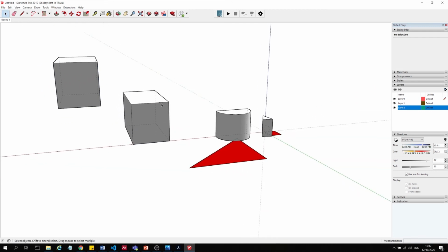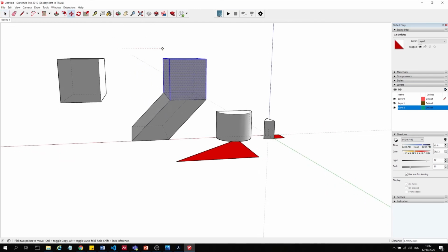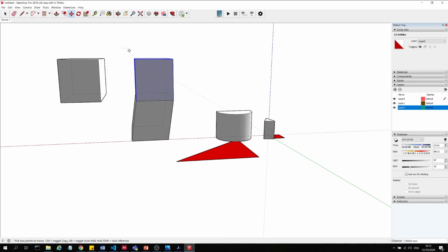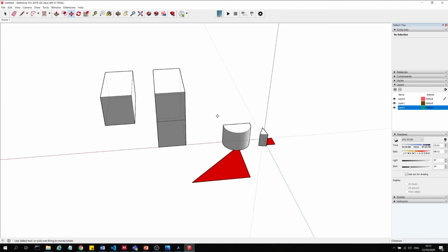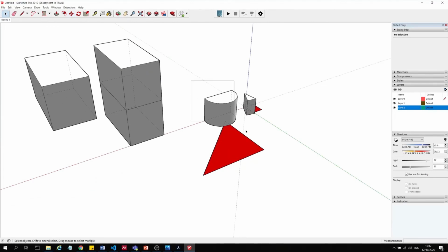Now if I have done the same with this object, so if I select and then I move again, so hold down Control and move, Escape, and now if I select this, I want to move, SketchUp will again think they're related because the lines are touching each other and the objects are not grouped. So this is very important to understand with SketchUp because this is one of the ways that really works in a different way when you compare it to other modeling software. So if you don't want anything influenced by any other geometries, make sure you group it.